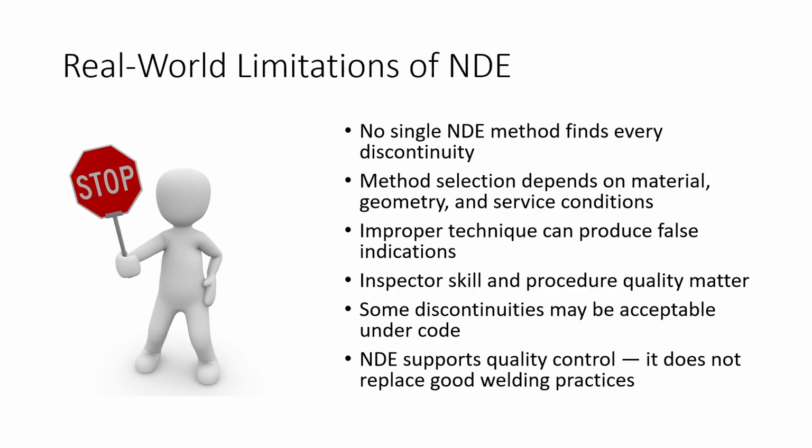Some inspection methods, you really have to have inspectors that are really skilled. And the procedure quality is going to matter. Who's doing this? How good are they? And not every discontinuity is a defect, and being able to determine that is kind of a skill in and of itself. So NDE does support quality control. It does not replace good welding practices in the real world.